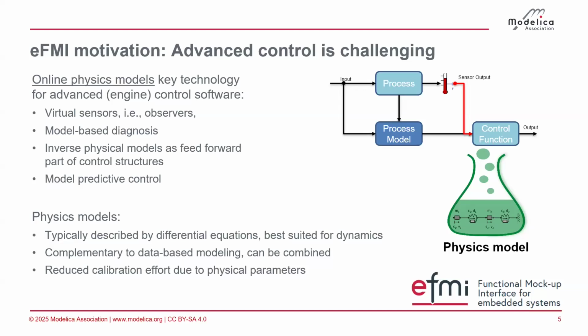There's no temperature measurement sensor in the battery cell, but you would like to know how hot your battery is to control it better. Then you could do a virtual simulation of the battery faster than real time and reuse from this simulation the virtual sensor value. So you take the physics from your process model, generate from it this predictor, get rid of the need for the physical sensor and inject that into your controller.